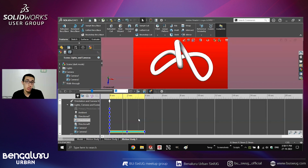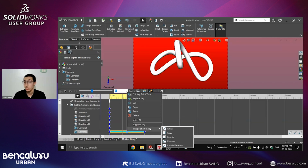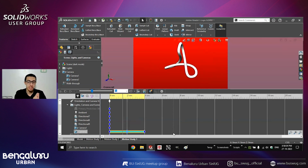And for example, as I said, interpolation isn't 100% based on the software. You can also provide it with some inputs. So for example, if I right click on here and hit interpolation mode, the default is linear. So for example, if it's like 0% over here, and after 1 second, it's 100%. So every 10 milliseconds, it changes 1%. So it's a linear scale, but you can change that. So for example, if I want it to be snap, what snap does is that it stays the same all up till the very last frame and then changes.